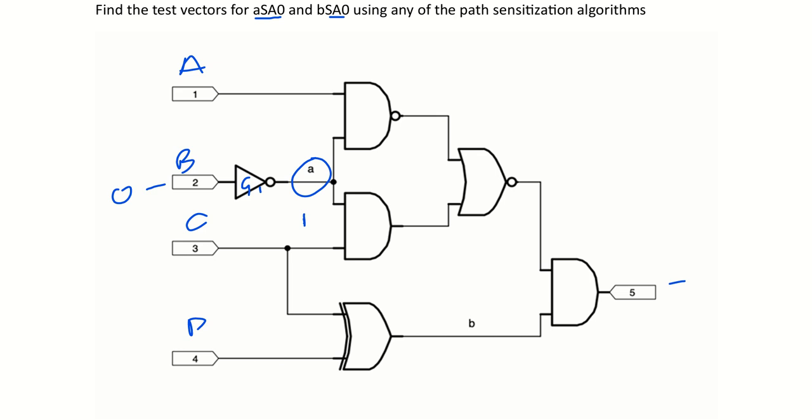So in propagating this error forward, the erroneous input at this point is feeding into this NAND gate and this AND gate. To be able to send this forward, we have to make sure that the output depends on the erroneous input, so that we can see its effect on the outside. So we have to make sure that the input C coming here is always 1.